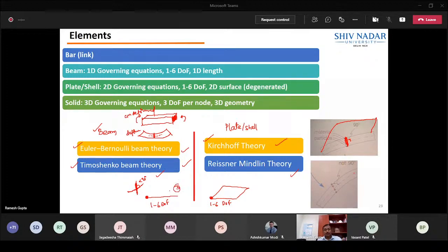Now, if the same one-dimensional element is available in space, then you have the x displacement, y displacement, z displacement, and rotations about each direction. So it is 6 degrees of freedom that you can have. In a similar way, even in the case of plate or shell elements, depending on what you are looking for, you can have only a displacement like a W displacement, two rotations, and axial displacements also. So that is where you have the displacements and rotations, 6 degrees of freedom up to that.